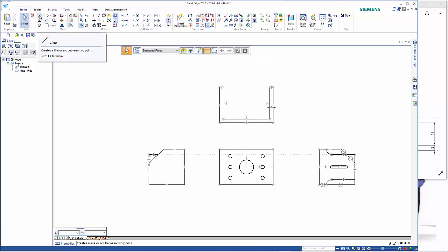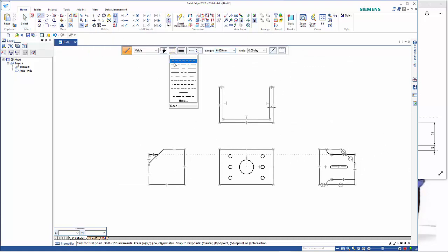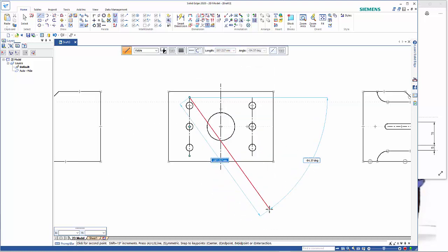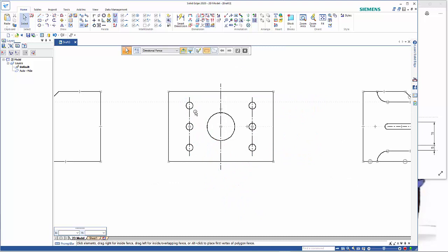So doing the center lines, we want to change this to a center line, and if I hit the S key I can do symmetric and just put that in there. Same again, S key, just to define those points. And then S key again, just hover over it and you should be able to get the center point in there,